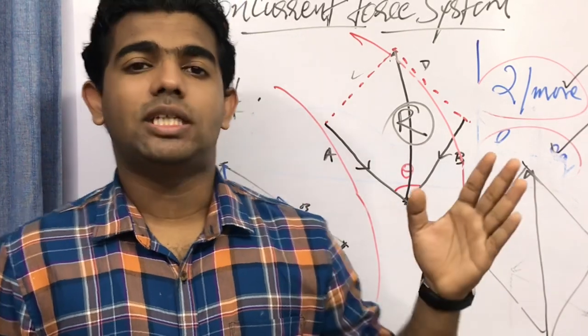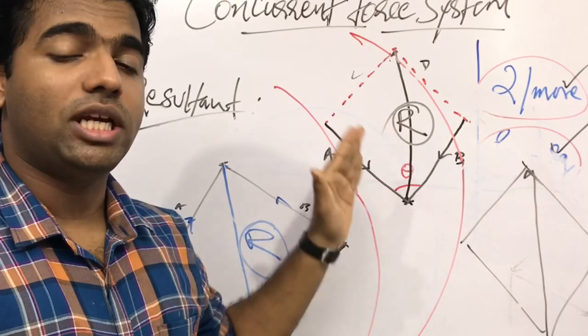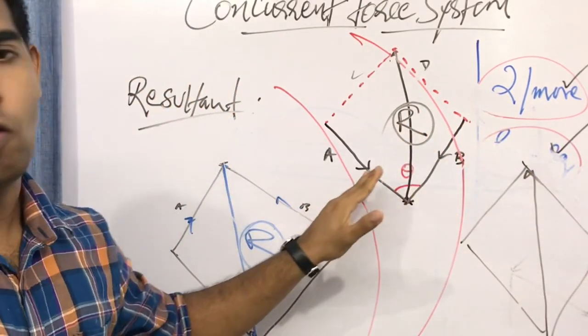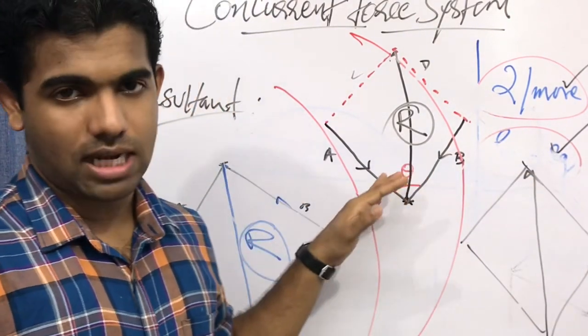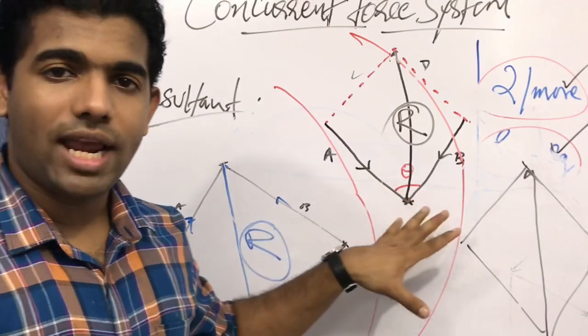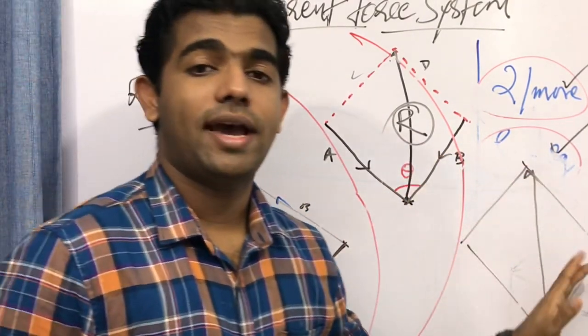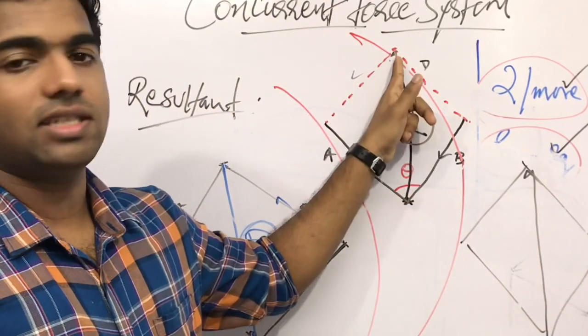You just have to write down that the resultant of a concurrent force system can be devised by the composition of a parallelogram. There we have the two forces A and B, or any other forces you can mention. Take some example, and now we draw a line parallel to the force B, and we draw another dotted line parallel to force A. Both of these lines intersect at a point.